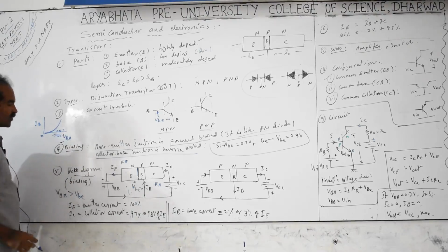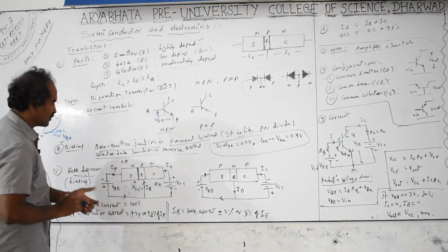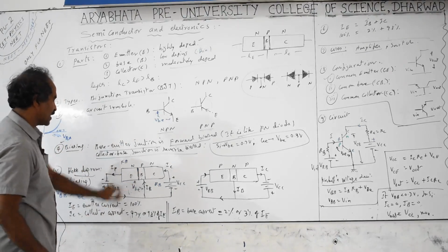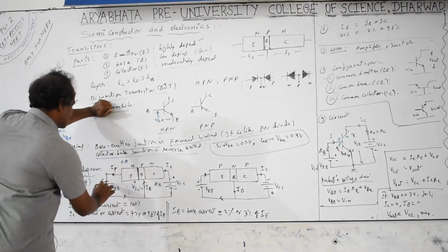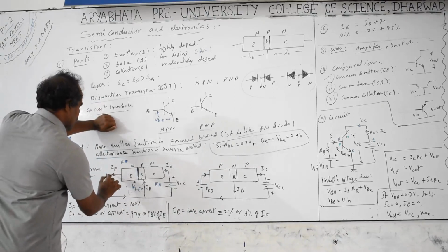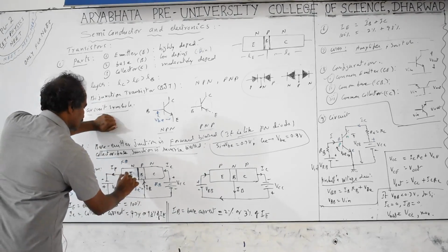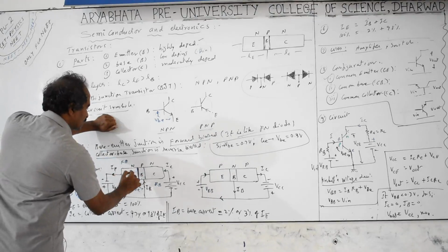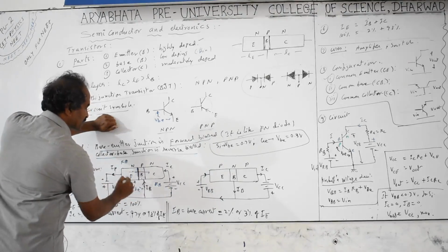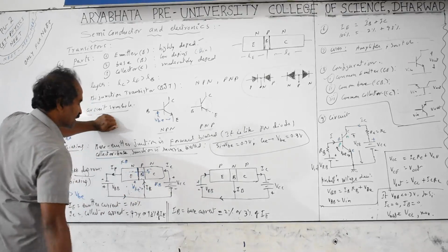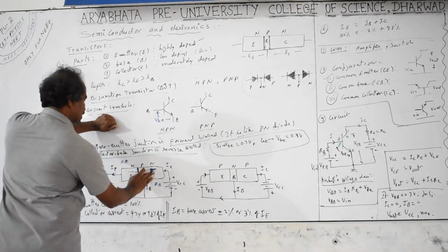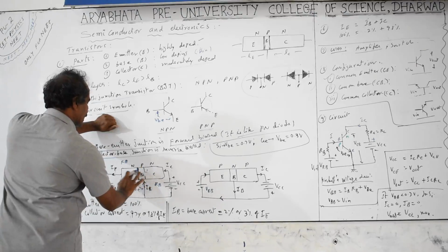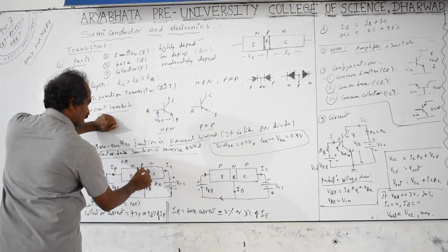This is like a forward biased diode, the same applies for the transistor for the first junction, which is forward biased, between emitter and base. Electrons will try to go from this minus. Conventional current is in the opposite direction. These electrons going in recombine with the holes, but the base is very lightly doped, so only a few holes recombine with the electrons. The remaining electrons, attracted by the plus terminal, go in this direction. This is the electron flow path, but the conventional current path we take is reverse, from plus to minus, opposite to electron flow. Some current passes as base current, from this recombination.